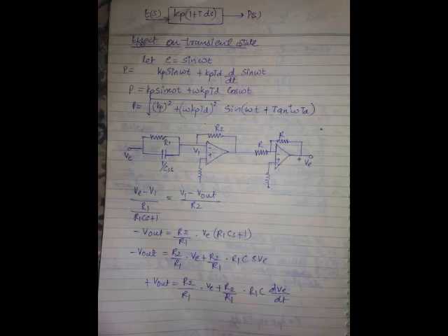You see, rise time and bandwidth are related to each other. Rise time and bandwidth are inversely related to each other. How they are related, we will see in the frequency domain specifications in the next topic. So, as rise time increases, bandwidth will reduce. So, what is the effect of this controller on bandwidth?